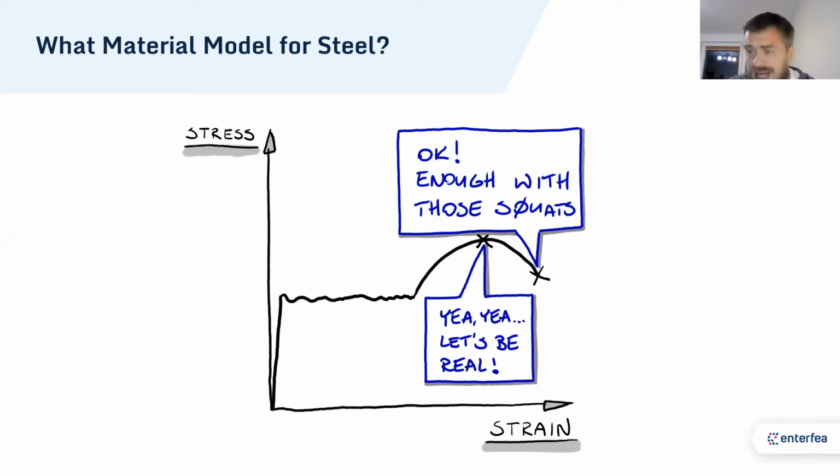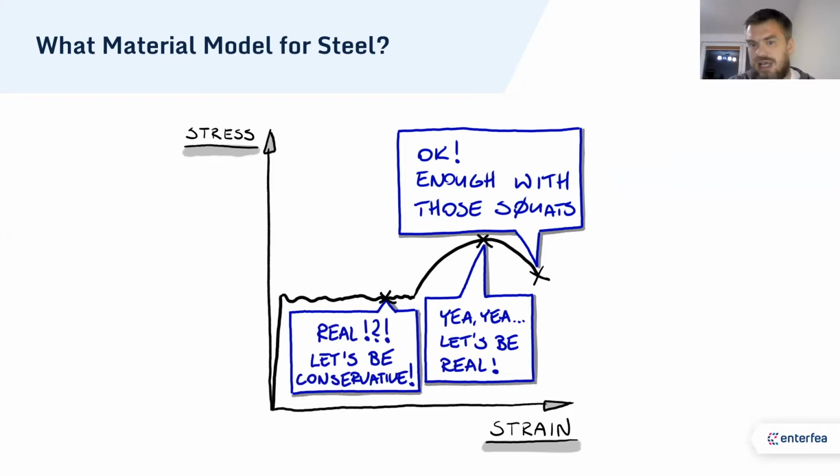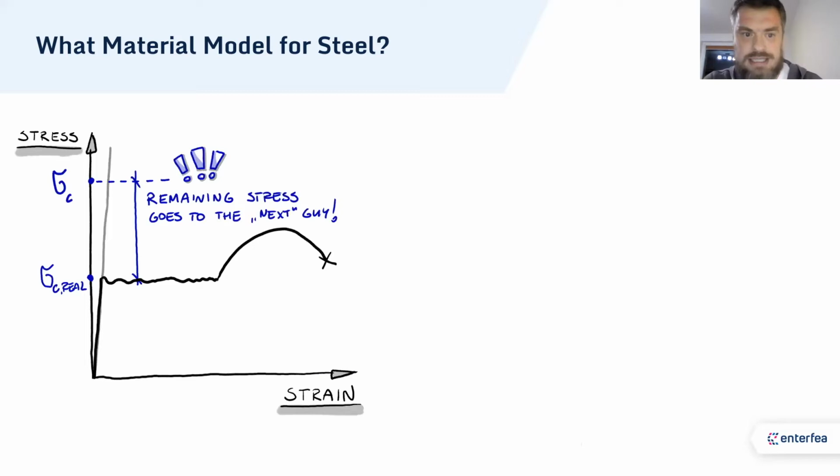So realistically, we should use a smaller value of plastic strains, but engineeringly speaking, you want to have a safety margin on it and so on and so forth. So there is a value you could derive from codes or procedures you enjoy and use in design to have the value that actually makes sense, right?